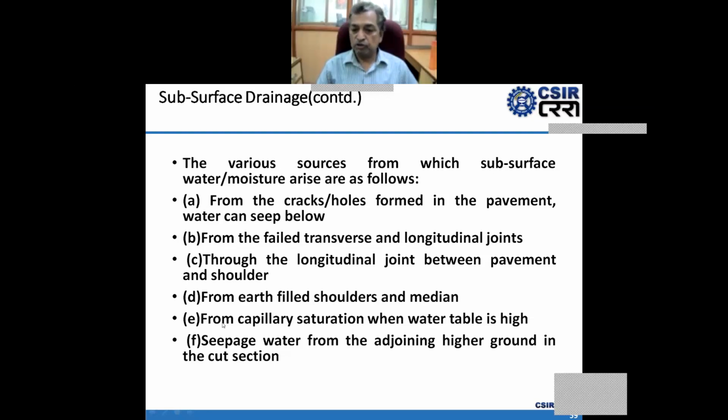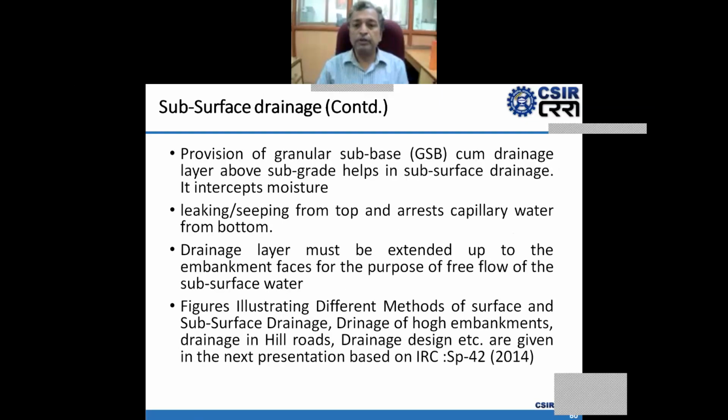From capillary saturation when the water table is high. Seepage water from the adjoining higher ground in the cut section. So these lead to the subsurface drainage system. So provision of a granular sub-base cum drainage layer above the subgrade helps in subsurface drainage.